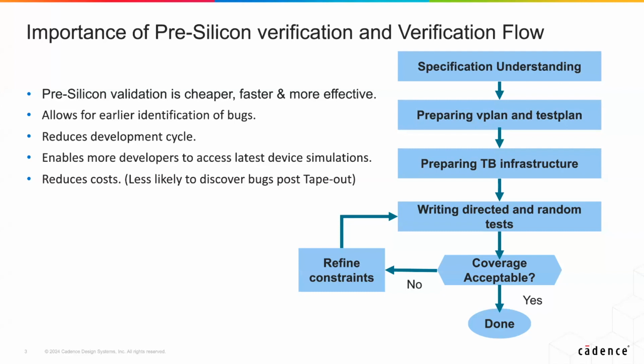After you have your test bench ready, you can start writing sequences. Sequences are basically network level transactions between the devices. And by doing them, you can target certain scenarios. For example, in a CAN device, there's a frame called data frame. You can send a data frame to see that your IP is handling, sending, and receiving the CAN data frame correctly.